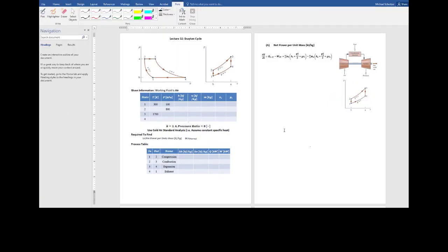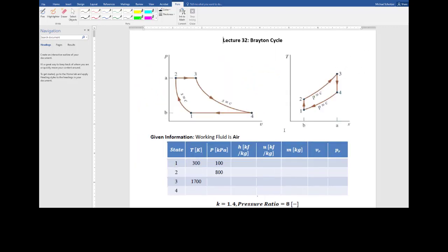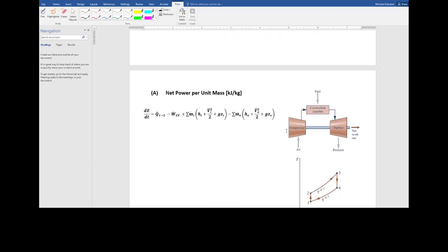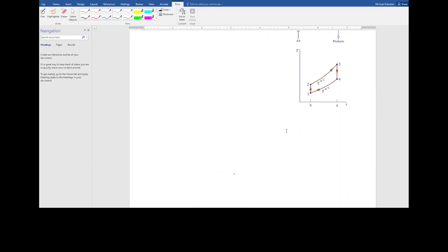Okay, so the first thing that we want to do, well, first maybe I'll go through, even though they tell us this, maybe I'll draw the TS diagram too, right? Because maybe we wouldn't have this right here, right? So the first thing that I always want to do if I have to draw a TS diagram is I want to count up the number of turbines and the number of compressors, the maximum here, right? It doesn't matter which one that I take because they're the same. And then I add 1.